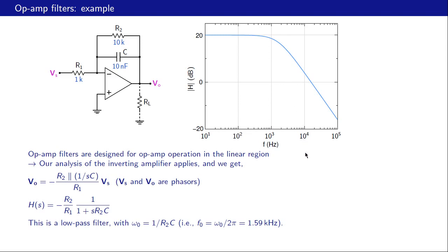This is the first order filter, and we can see that from this function as well as from the plot here, this slope is minus 20 dB per decade. There is the circuit file available to you, so you can change, let's say, the C value or R1 value and predict what's going to happen, and then see if that indeed happens.